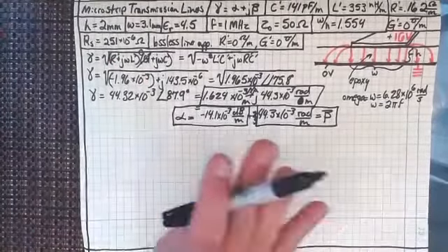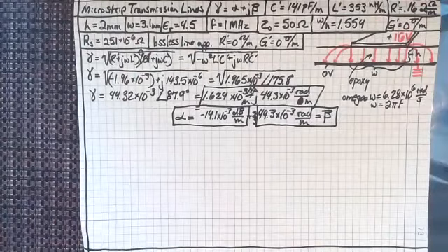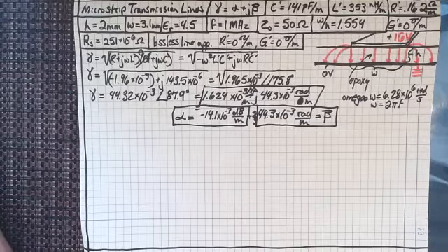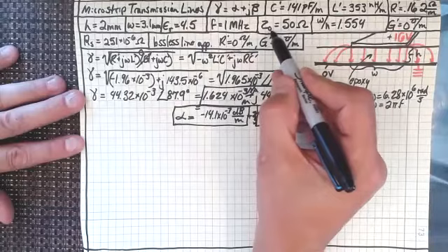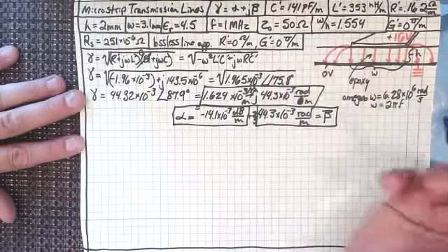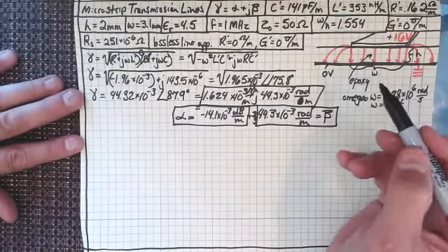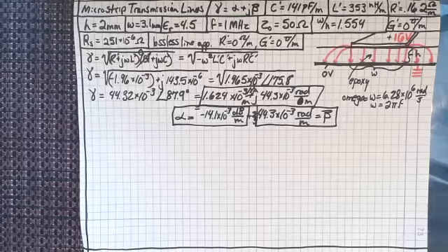There's no attenuation. Basically, across the phone there are such short distances that you don't ever have to do anything but look at lossless line approximations. And that's what we did here, if you remember, when we used the characteristic impedance to find out what the W over H ratio was, okay? So we've got that, and I think everybody can see that, yes, we don't need it.